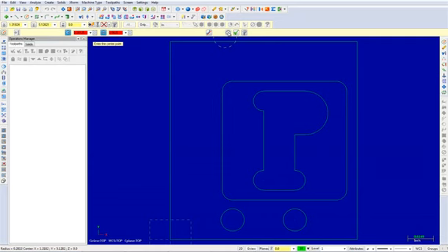Select the fastPoint command again and input the following coordinates, 1.5, 4.5, and press enter. The third arc will appear as shown. Select the Apply button to stay within this command.